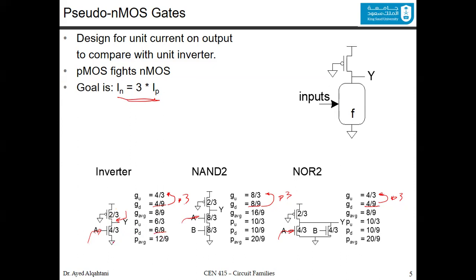That's the parasitic in the down. In the up, you multiply it by 3, similar to what we've discussed. Here you have 2/3 and 8/3, which is 10/3. If you divide it by 3, it's 10/9. You will divide by 3 again to compare it to the CMOS inverter, and then you get this one by multiplying by 3.